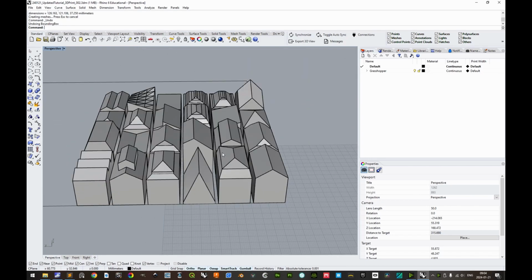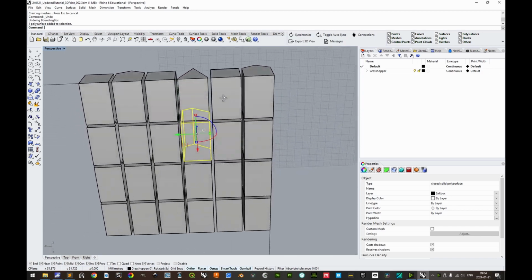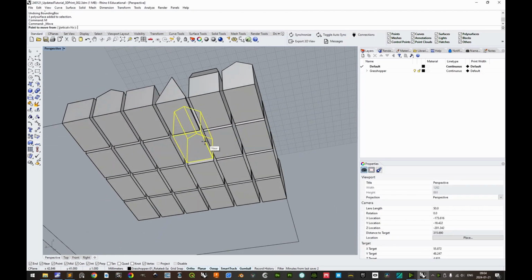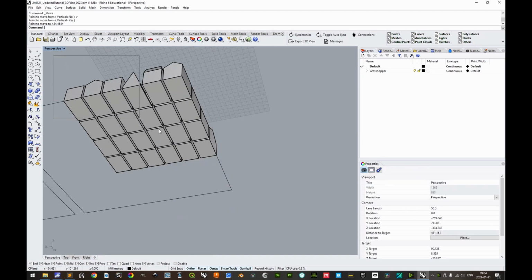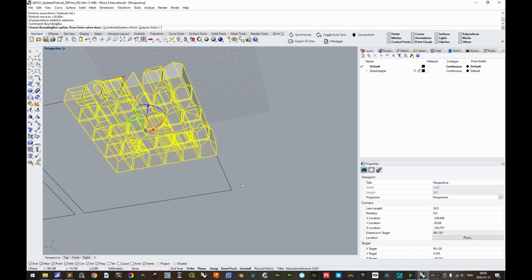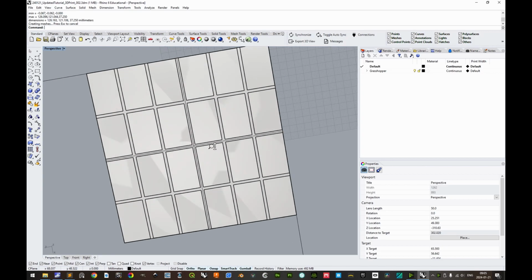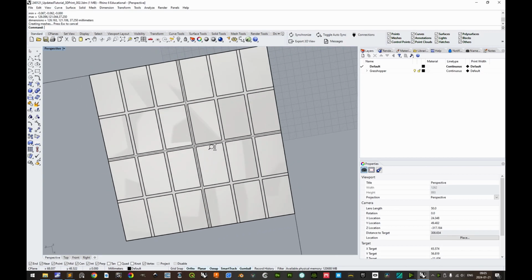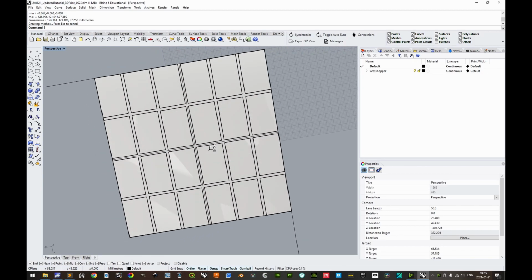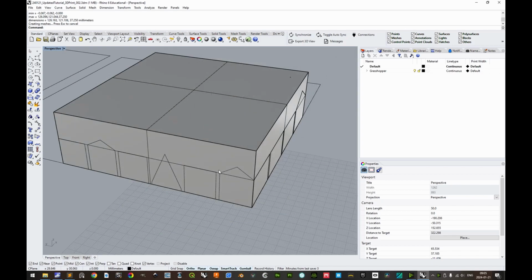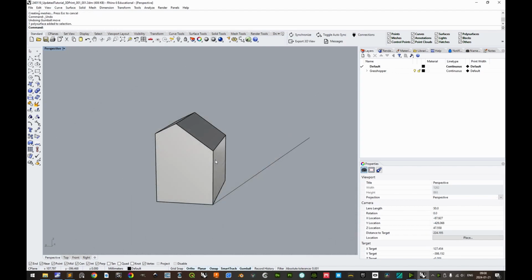Ctrl Z to undo the bounding box, identify the object, which we previously did. Move, constrain movement to vertical axis, select suitable bottom corner point, and align it to any other. Now repeat the bounding box. Now that we can see that all bottom surfaces are properly Z-fighting, we can assume that all bottom surfaces are horizontal, which they should be. Ctrl Z to undo the bounding box.